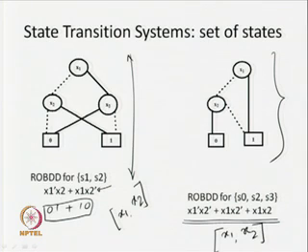X2. With this particular variable ordering, we are getting this BDD, and this is basically the ROBDD for this particular subset, because we cannot apply any more reduction rules to this BDD. So, we are getting the ROBDD.